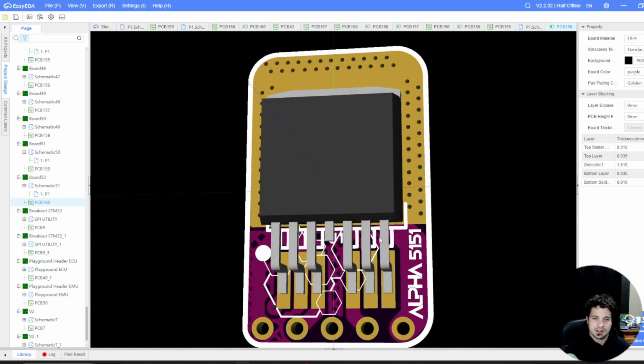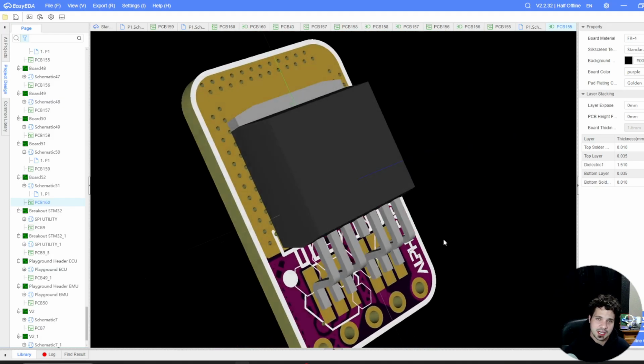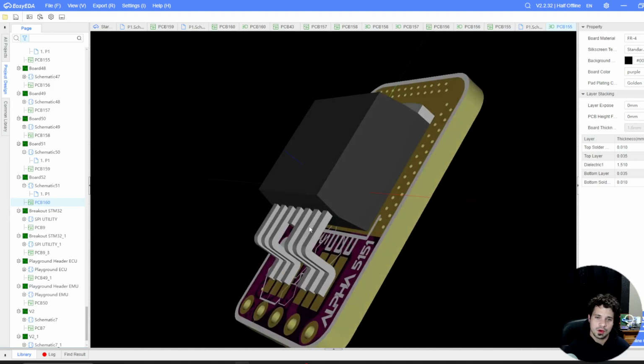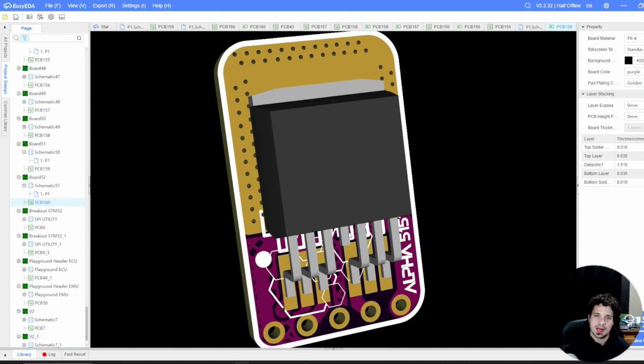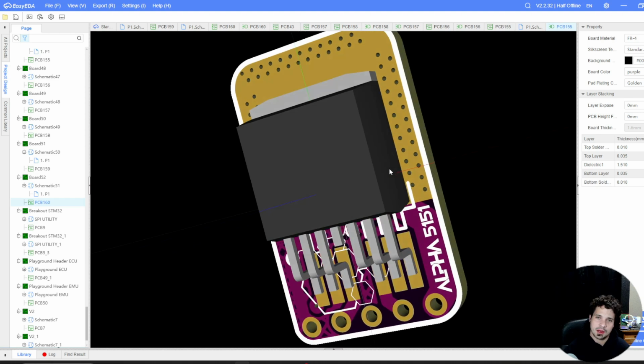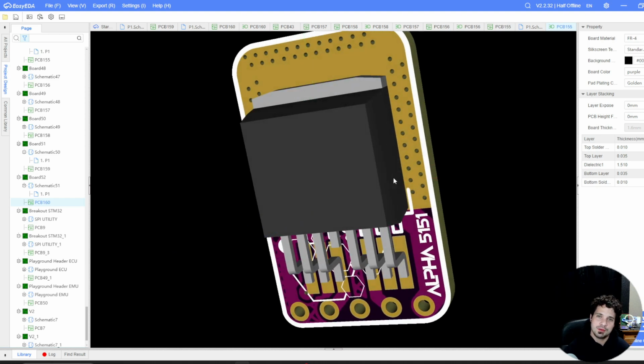What we have here is an IC that is a high side switch. So the 5151 that is used for switching VTEC on and off is what's known as a high side switch. And what the high side switch does is it allows us to take a positive rail, being the 12 volt rail, and inject it from an input to an output.